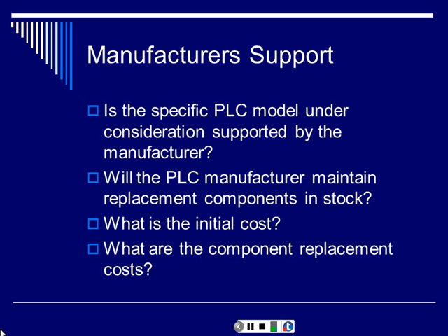So the model, considerations for support: will the PLC manufacturer maintain and replace components? If it breaks, how am I going to get it fixed? You know, is it obsolete tomorrow if I buy it today? The initial cost, you know, that may be some consideration, but I would more consider what support I could get in replacing things, adding things, and upgrading. Okay?